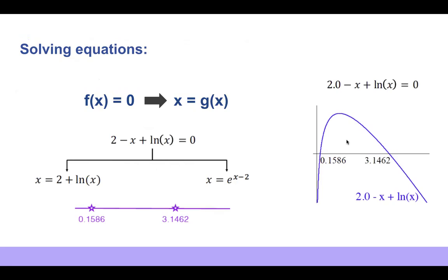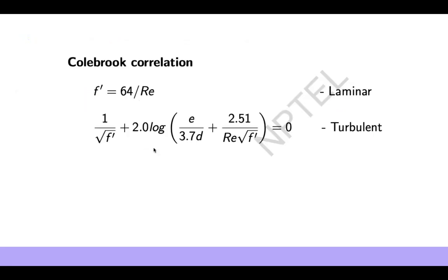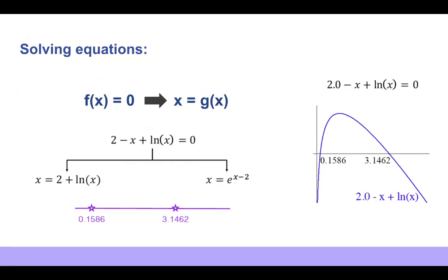Now coming to solving this equation, this is where MATLAB mainly comes in. The laminar formula is very straightforward, so you can try and find out the friction factor manually. But when you come to the turbulent region, you have to solve this equation, and it is not straightforward. It's a bit difficult when you're trying to do it manually. So for that, we'll use inbuilt MATLAB functions that can help you solve the problem. There are already several MATLAB solvers available.